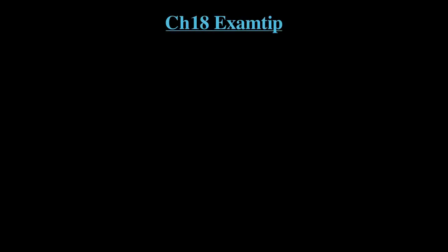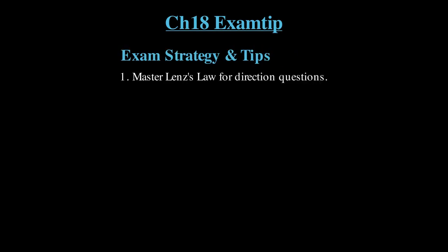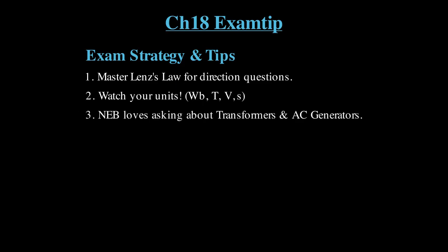To score maximum marks in this chapter, here are my top tips. First, truly master Lenz's law. It's the key to all conceptual questions about the direction of induced current. Second, always watch your units and be consistent. The NEB loves to ask about the working principles and energy losses in transformers and the AC generator, so prepare those theoretical questions well. A very common mistake students make is forgetting the number of turns, N, when using Faraday's law. Don't let that be you. Remember these points and you'll do great.